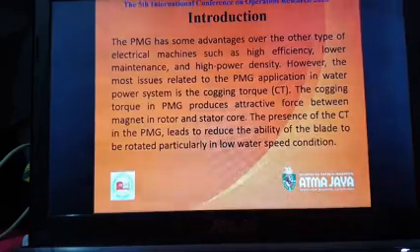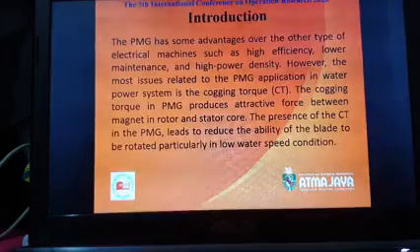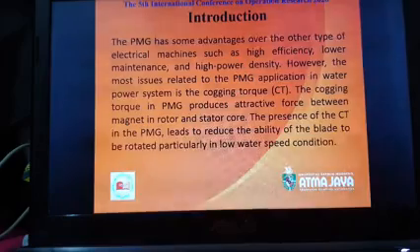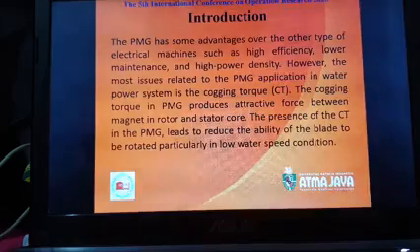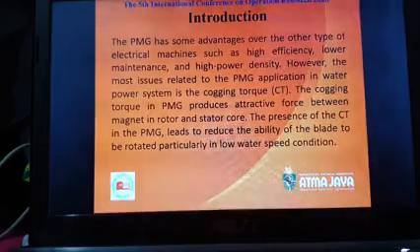investigated in this study. For the purpose of the study, a fractional slot number of 24 slots and 8 poles has been selected. The permanent magnet machines studied in the paper are inner rotor prototypes with radial flux distribution. 3 different structures of permanent magnet machine were analyzed numerically, and the results regarding their performance were compared.